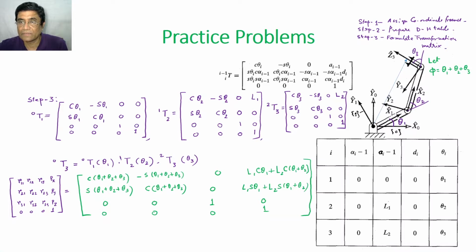So x1, the unit vector x1 cap, y1 cap, and z1 is perpendicular to the plane of the paper or the display here. Okay, so you understand, and then joint 2. This link's body coordinate frame is x2. So again, x will be directed in the direction of the common normal, perpendicular to the axis, and y2 and z2 are such that z2 is perpendicular to the board.